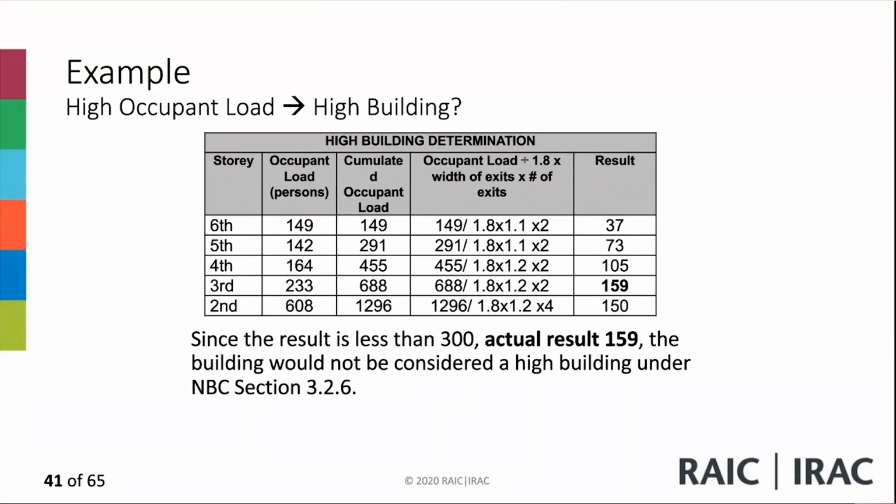You do some cumulative adding up of exit width capacities, and added floor areas to accommodate that number of people. But that's different from a typical floor area. You don't do cumulative exits. You take it floor by floor because you assume people from the lower levels have already gone out, so everybody is discharging at the same time. Thank you.